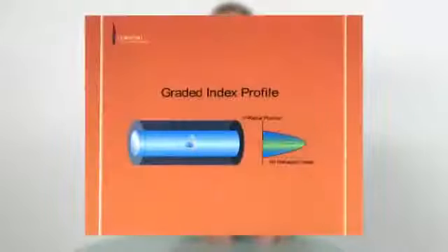A higher bandwidth fiber does a better job of getting all the modes to the receiver at the same time. The practical measurement for comparing one fiber's differential modal delay to another fiber's differential modal delay is called bandwidth. Higher bandwidth preserves the transmitted pulse better, improving the receiver's accuracy in discerning ones from zeros. That is, minimizing the bit error rate.